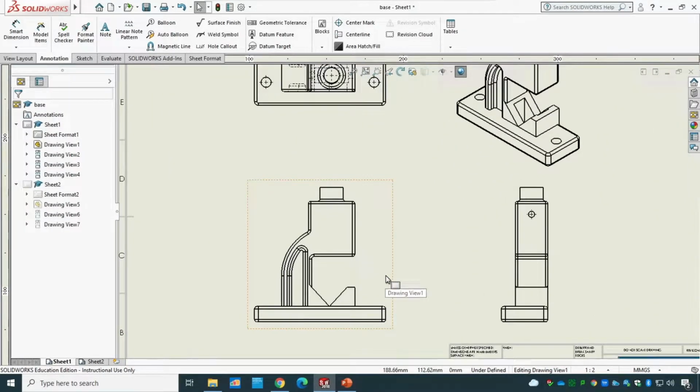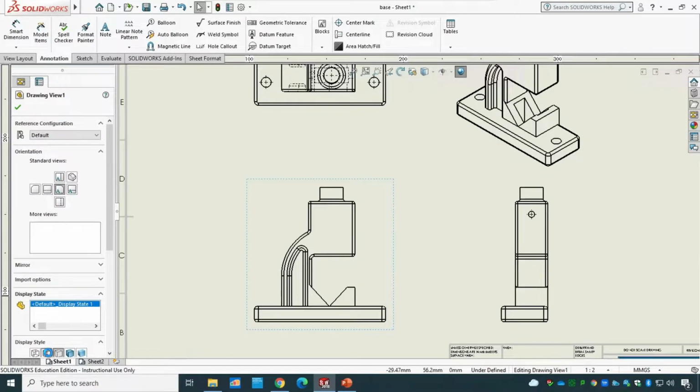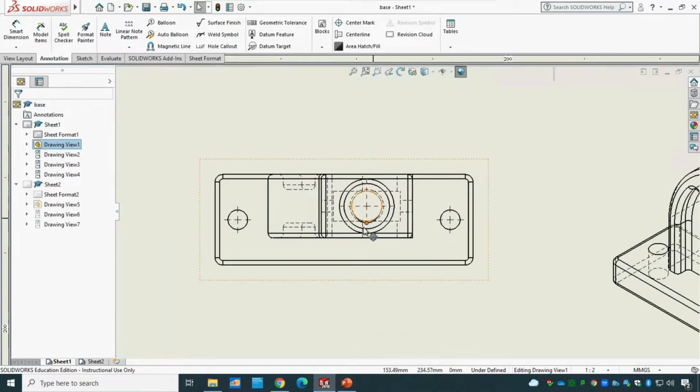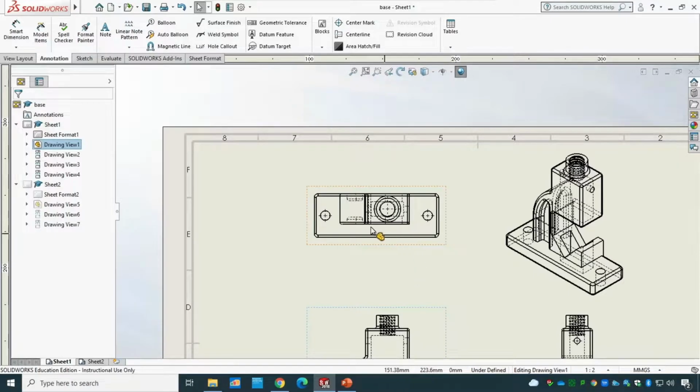The main goal of the technical drawing is that you want to have a report, a document that is simple but easy to follow. Here you can see I don't have enough information, because I want to see what's going on with the holes that I have there. So it's better to bring back the hidden lines. However, the hidden lines in here make it complicated. You don't get so much information there, to be honest.